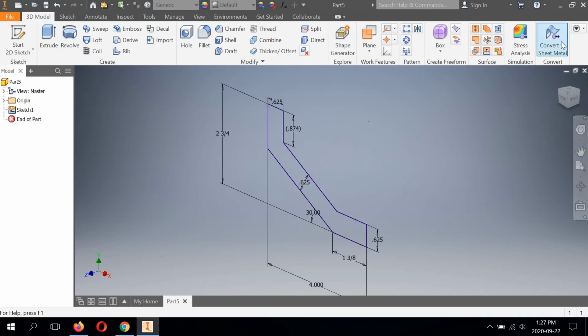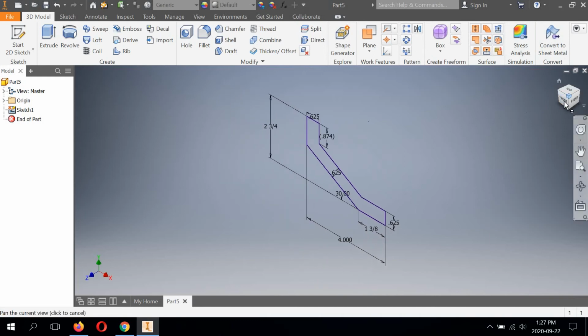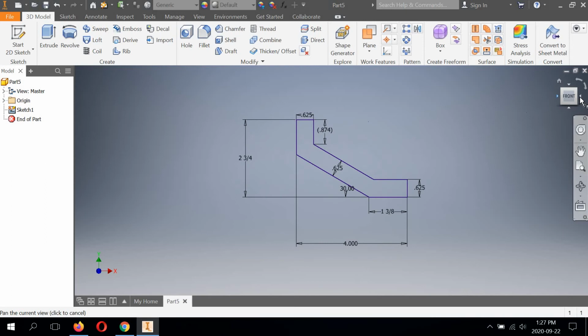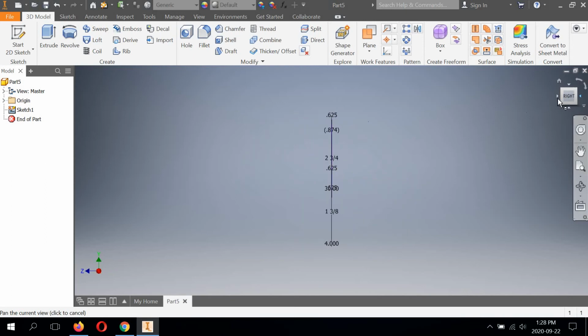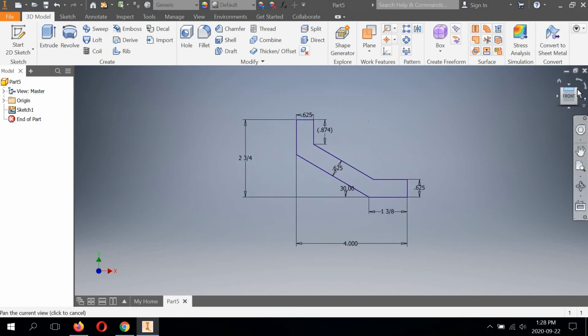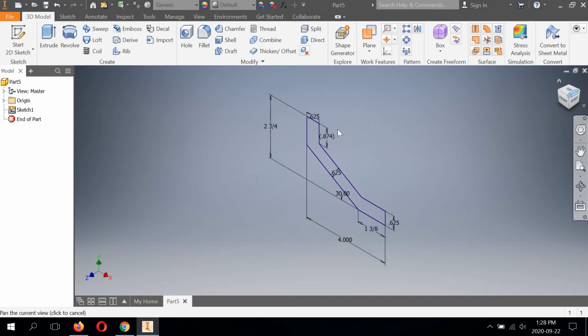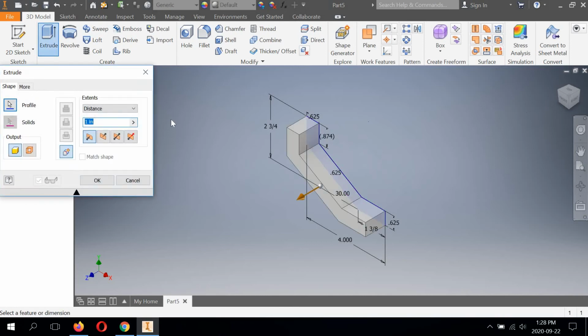So now that I've hit finish sketch, this is going to bring us into an isometric view, right? Here's our front view of the sketch. We have no depth to the right side. So we'll just hit the corner of the cube, put this on an isometric 3D view, and hit extrude. We're going to give it depth, make it a solid on the z-axis. It doesn't give us an overall width that we can extrude this with. It gives us 3 fractions. It says 9/16, 1 1/8, 9/16.